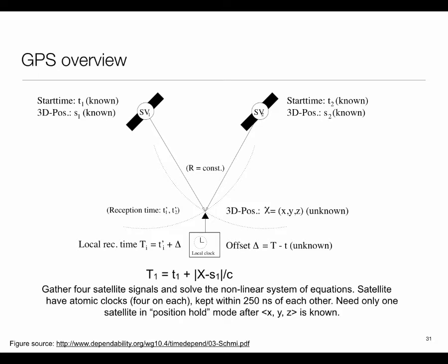One of the things I used them for in our devices is indeed the GPS receiver. GPS has to internally calculate time, but it doesn't always expose it. Most GPS receivers expose it through some sort of serial port or just display it, but that's too inaccurate, because by the time you get to read the clock, some amount of time has passed.